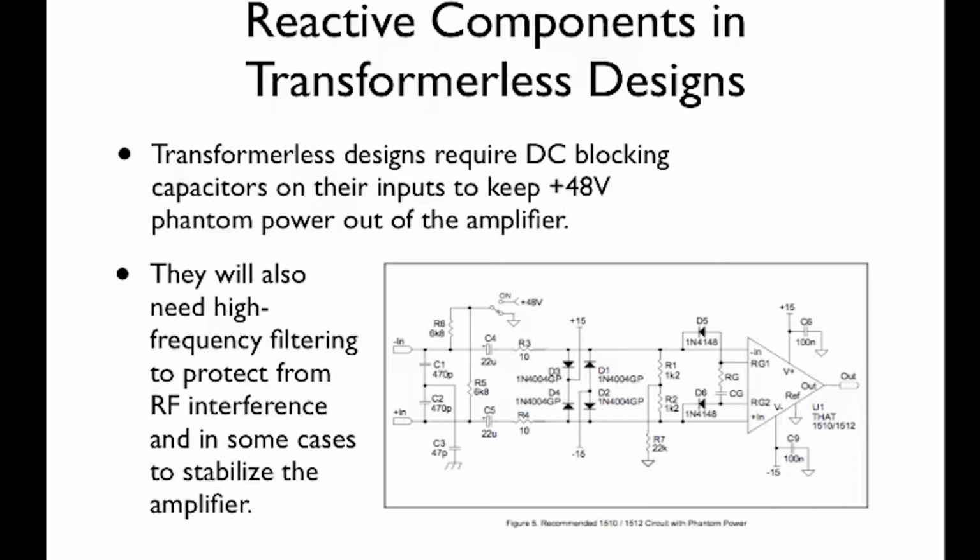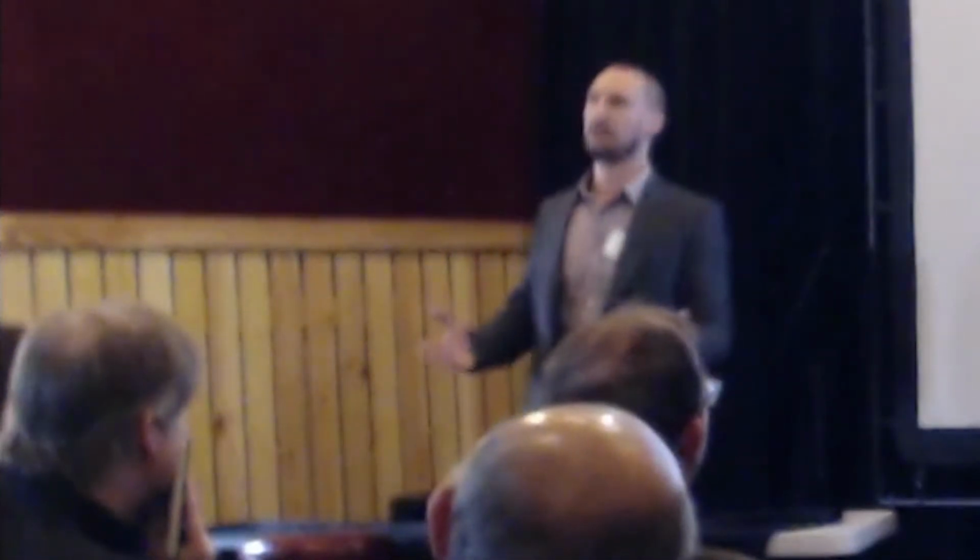So the value of this capacitor and the value of this resistor, which also, by the way, sets the input impedance of the microphone preamplifier, will determine the low frequency extension of the design. So I want to make sure I choose values that put the input impedance of the microphone preamplifier where I want it to be, while also not having a significant amount of roll-off in the audio bandwidth. Generally I would want that to create a filter below 20 hertz. And I would want the capacitors here to be able to create a filter that at least begins to attenuate by maybe 200, 300 kilohertz.